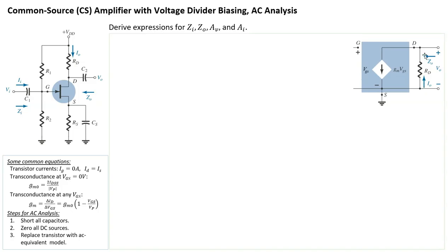And then on the input side, if you remember, there is no current going into the gate. VDD becomes 0 volts, which means the top part of R1 is now grounded. And since R1 and R2 share the same node in the middle, R1 and R2 become in parallel, because the top part of R1 is now shared with the bottom part of R2.